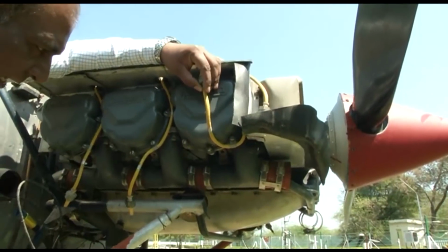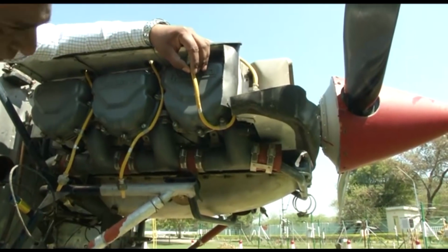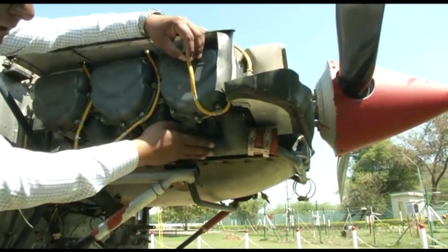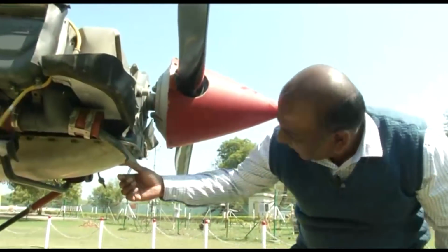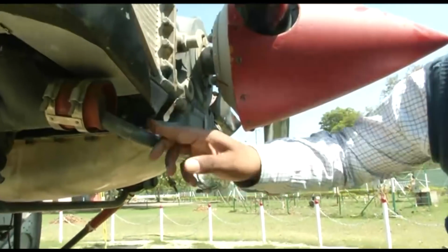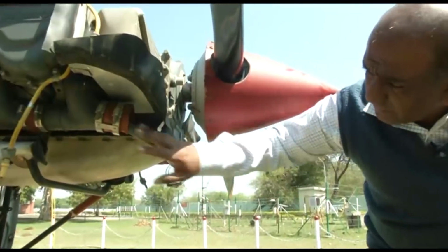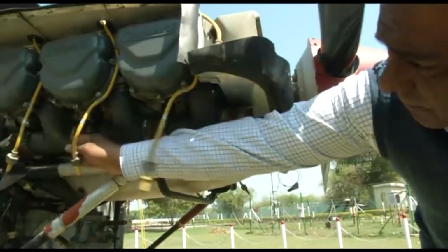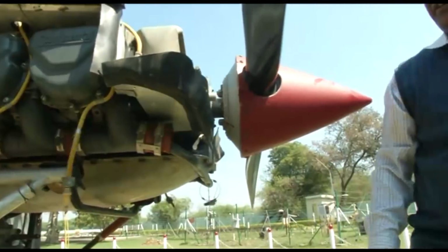You have seen in the case of a downdraft that these were moving in the downward direction. This is one bank on the right side, and a similar bank on the left side. In between the two banks, as we have seen in our slides, this is your balance tube to balance the air between the two banks. One bank on this side, another on this side, a balance tube, and an updraft system. All the ports move in the up direction, so this is called an updraft induction system.